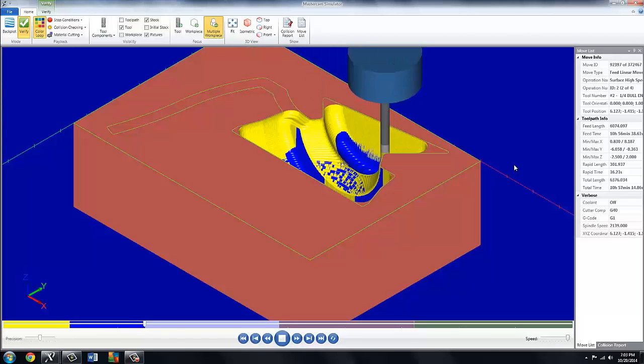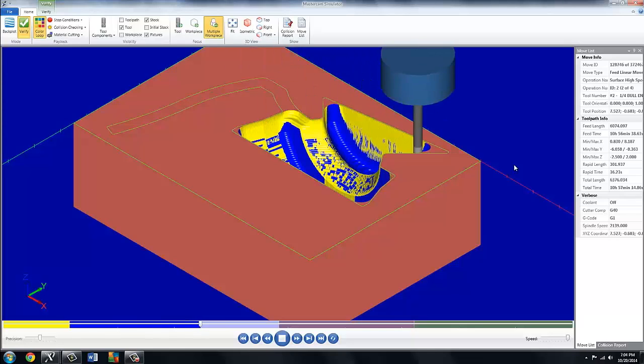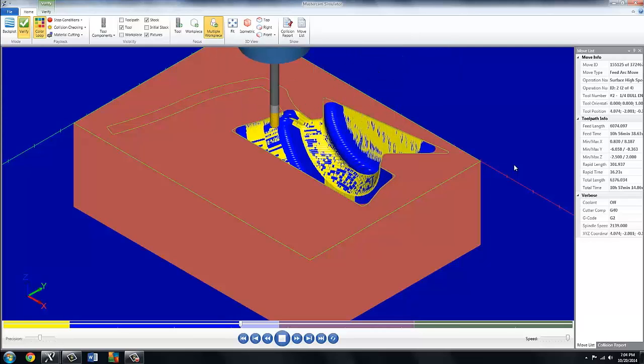So we did the surface high-speed opti area, now we're doing the opti rest toolpath. Then we're going to go into the hybrid for finishing, and then the scallop to pick out the rest. And our end mills get smaller every time. And that's the efficient way to do it, because you want to take out as much stock as possible with the biggest end mills. You'd be forever trying to do this whole job with a little end mill. So that's the thinking behind it.